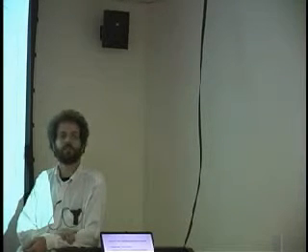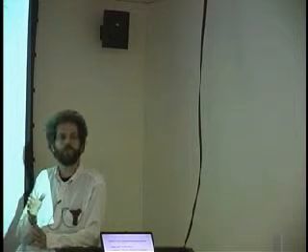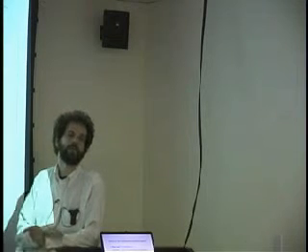In other words, we're only going to have a single read-write port to the main memory. Most of the time it's going to be used for doing reads, for reading the instruction to be done. Occasionally when the instruction is a load or a store, after we do the read to find out what the instruction is, we'll stop, we'll do the load or the store in an extra cycle, and then we'll pick up from where we left off.